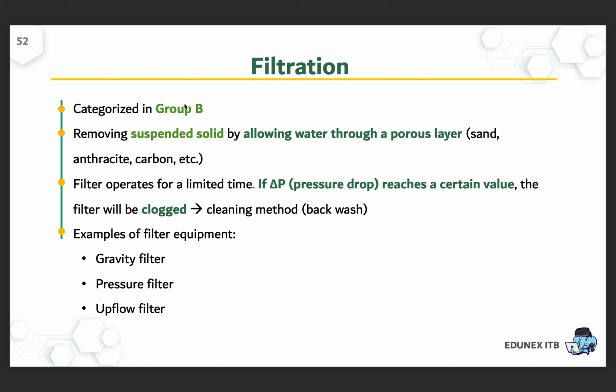In group A, it's basically conducted to remove the non-suspended solid, and we have sedimentation, then clarification and aeration. And now we will move to group B, water treatment system. Group B is the filtration system. In the filtration, the aim is to remove the suspended solid by allowing the water through a porous layer.